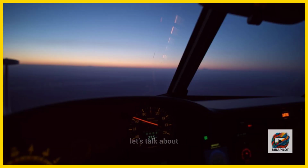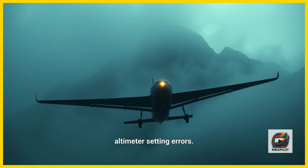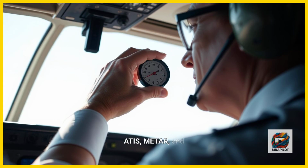Speaking of mismatches, let's talk about altimeter setting errors. Using the wrong QNH can lead to vertical separation violations or even CFIT, controlled flight into terrain. Cross-check ATIS, METAR, and ATC clearance to ensure your altimeter is set correctly.